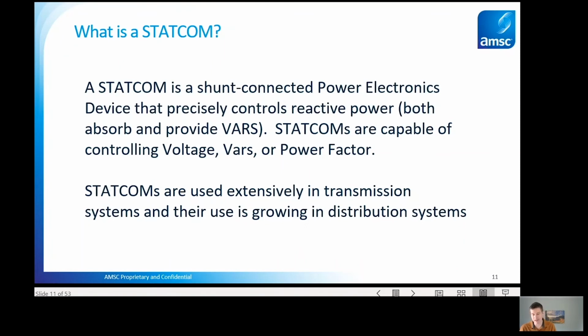So by being optimized to just process reactive power, there are some optimization tricks that can be played that you can't get out of traditional inverter technology. StatComs are capable of controlling voltage, VARs, or power factor, depending on the application. StatComs have been used very successfully and extensively in transmission systems, and their use is growing now in distribution systems as product offerings have now become available for distribution applications.